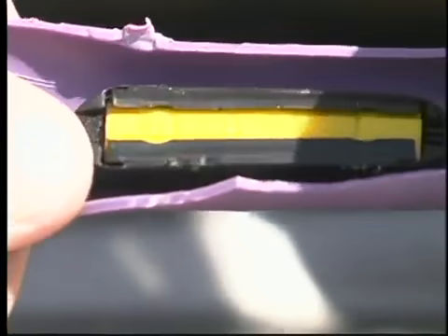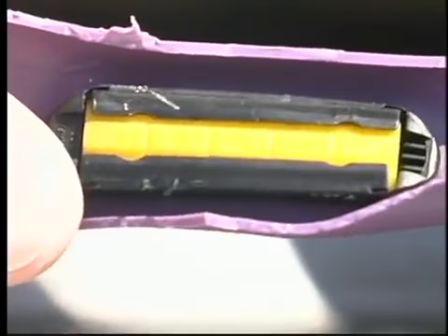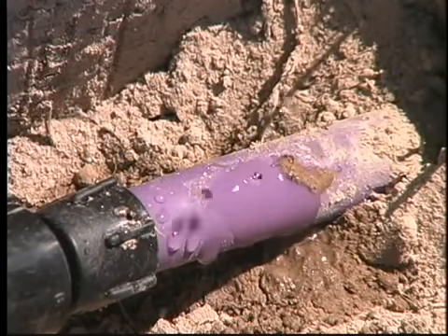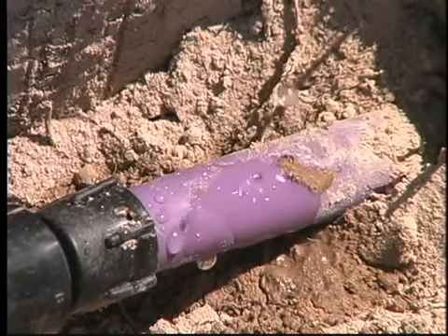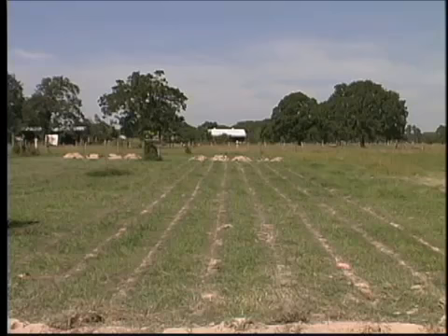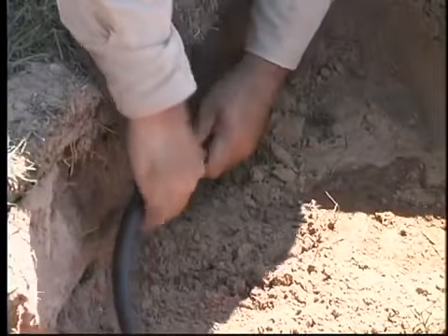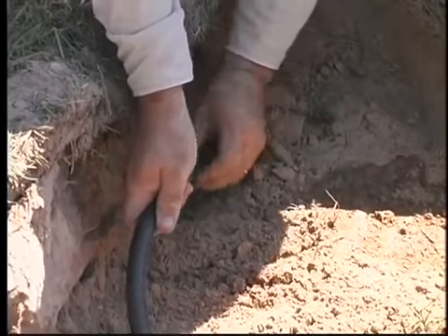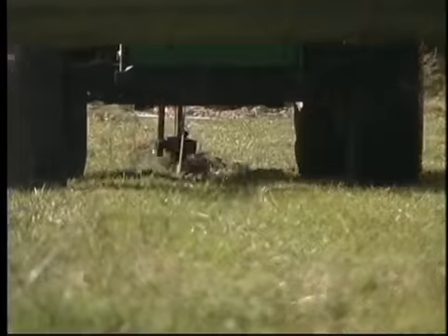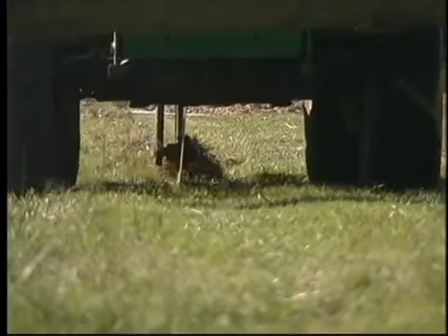The system relies on drip tubing with emitters to reduce the water pressure before it enters the soil. Since the emitters in the line have the same emission rate, wastewater is uniformly applied to the dispersal field. The drip field is constructed to spread water across the landscape. Tubing is placed approximately 2 feet apart in the landscape so the emitters are on a grid pattern. The drip lines are buried relatively shallow so the soil can provide treatment and landscape plants can use the nutrients and water. The tubing can be placed within the existing landscape.